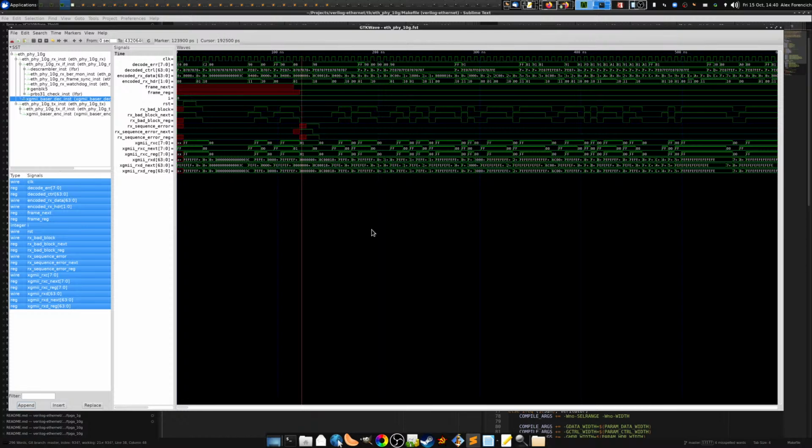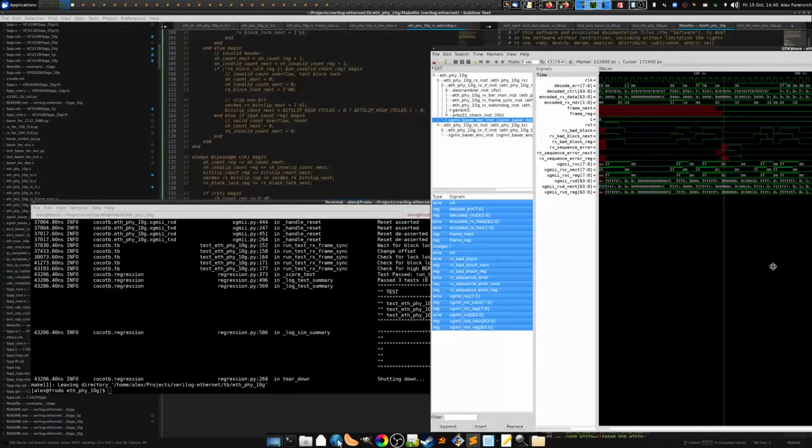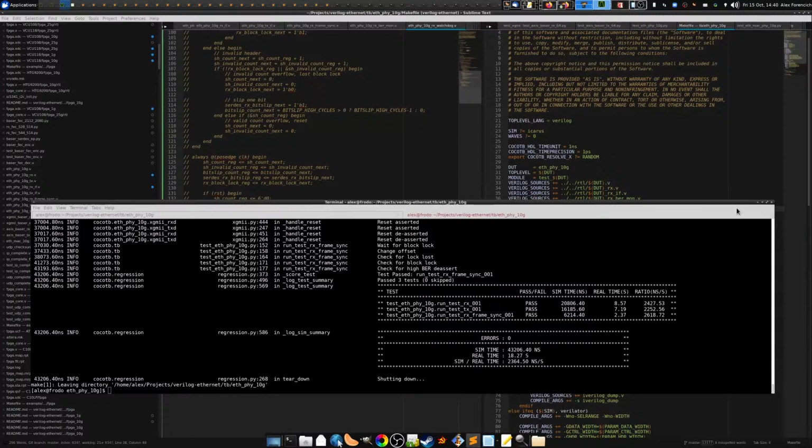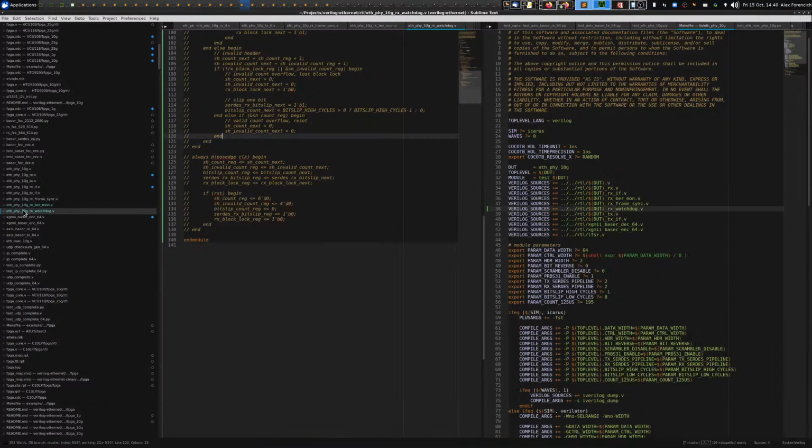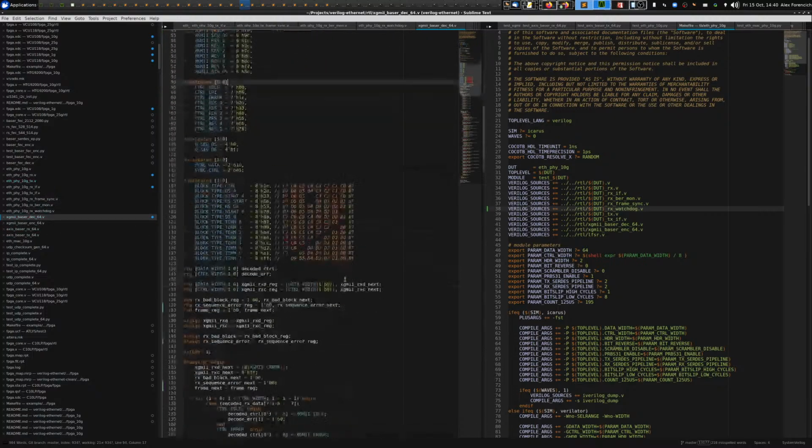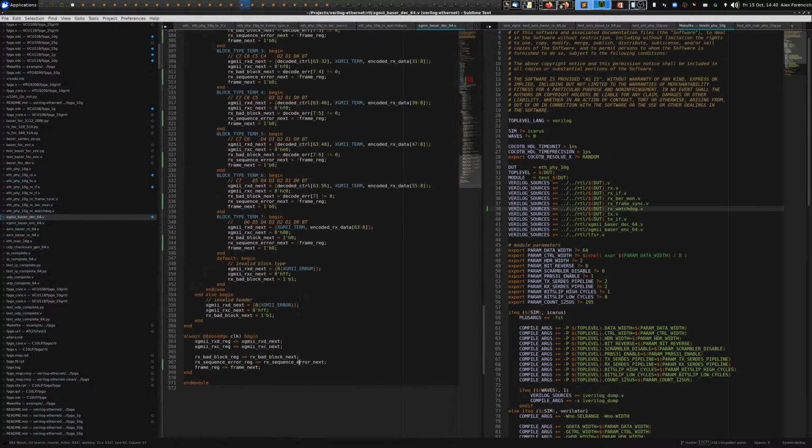Okay. I get an X because the frame was an X. All right, let me go ahead and add a reset then for that. That was in the decode module here. I have a reset connection, I'm just not using it for anything right now. Okay, so if RST, then I can do frame reg. I will set that back to 0.